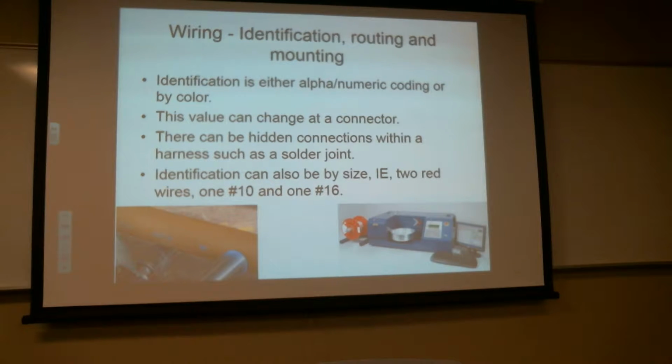Another thing that can occur happens for one of two reasons. Somewhere in the middle of the wiring harness, you might see a wire that's just soldered together, fully insulated, wrapped up and bundled in the harness. That can occur where two harnesses come together and they really only interface on that one wire. So they'll leave it strung out and that part of the harness very loosely wrapped, bolted all in the airplane. Once it's all in the airplane, those two wires are brought together, soldered, insulated, and then everything is triced up appropriately. So you might see that.